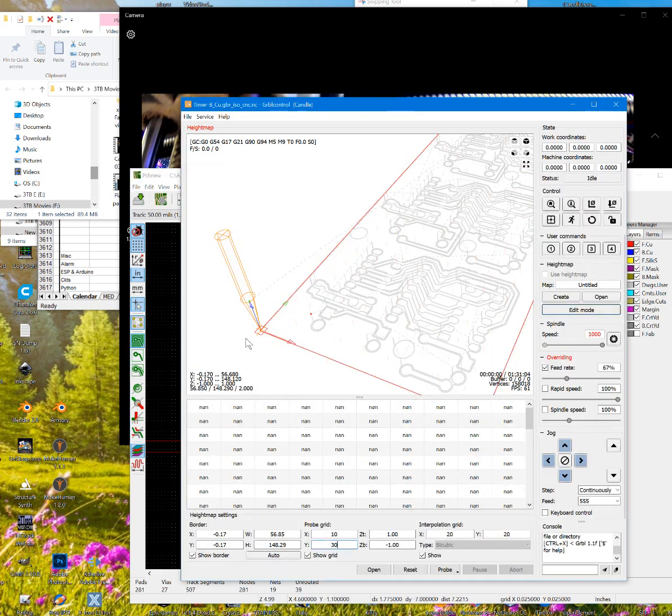So 2.3 inches, well, 2.39 is about 2.4 inches. So it's about every 2.4 inches, since I got 10 across, 10 along the x-axis, which is here, that means it'll be 10 divided into 2.4 inches. So it's about every quarter of an inch it'll do a test point. In order to maintain that, since this board's about 6 inches, if that was 4 test points per inch, it'd be 24 test points. The 30 will be fine, so it'll take a little longer.